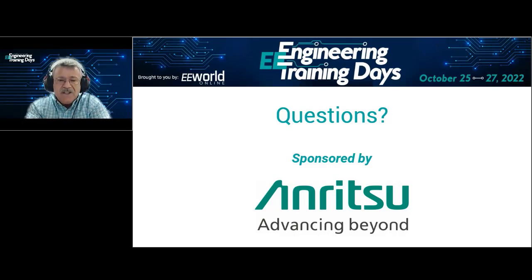So on the SiteMaster products, let's say you calibrated in the truck because it's cold outside, and then you get outside and start taking measurements and the temperature starts getting cold. The analyzer will alert you and pop up a message to tell you your calibration's not valid any longer, and then you can do a new calibration at that different temperature, and it will hold that until the temperature changes by a certain amount.